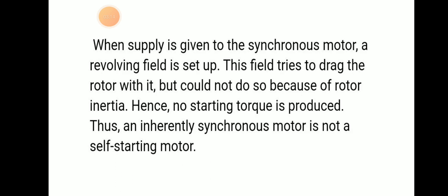But when supply is given to a synchronous motor, a revolving field is set up. This field tries to drag the rotor with it, but it cannot do so because of rotor inertia. Hence, no starting torque is produced. So, an inherently synchronous motor is not a self-starting motor, and we need external help for starting. But asynchronous motors are self-starting motors. Due to the two types of flux that are produced inside it, it will automatically start rotating.